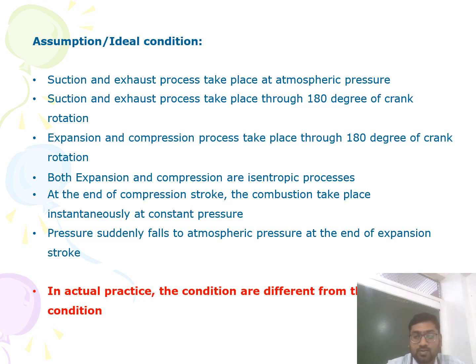The next assumption is that at the end of the compression stroke, the combustion takes place instantaneously at constant pressure. It means the sudden combustion of the fuel takes place. The last assumption is that the pressure suddenly falls to atmospheric pressure at the end of the expansion stroke. So during the heat release process, the pressure built up during combustion suddenly drops to atmospheric pressure. So this is about the assumptions for the four-stroke diesel engine.